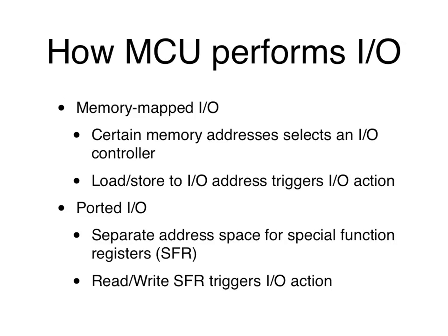So for example, if you want to receive a packet from an Ethernet controller or send a packet to an Ethernet controller, then with memory mapped I/O, you might say, I know this memory address corresponds to the Ethernet controller. Then I just keep writing to this address or keep reading from that address. So that's one way to do it.